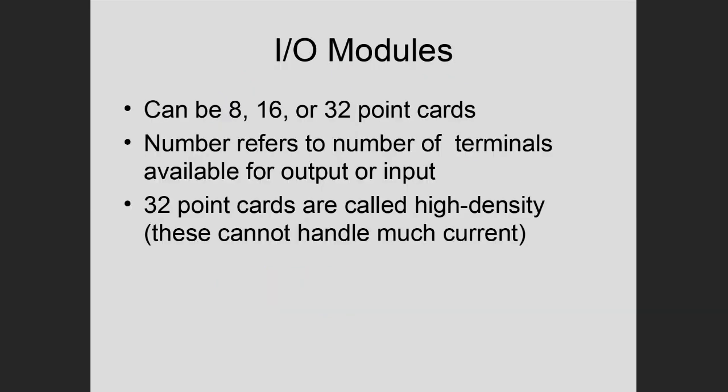I don't care too much about this. This is just when you deal with I/O modules, a point is the number of connection points you have. So I can have one with 8 screw terminals you can connect 8 switches to, so they call it an 8-point card. Typically you can buy an 8-point card, a 16-point card, a 32-point card, and they actually make them smaller than 8, although when you get smaller than 8, I don't know if you would call that a PLC. You probably call it a microcontroller.